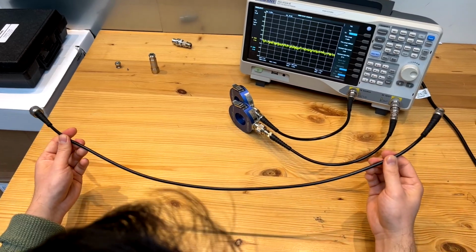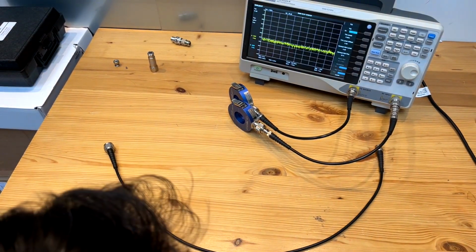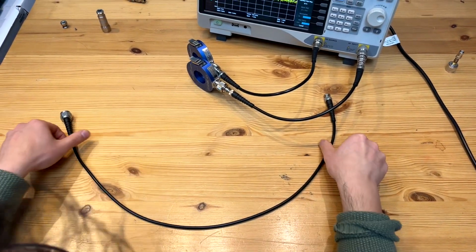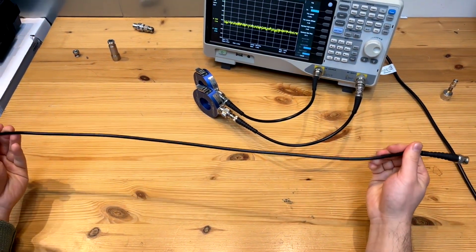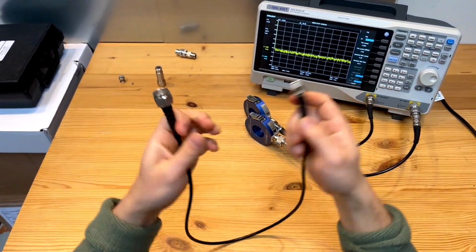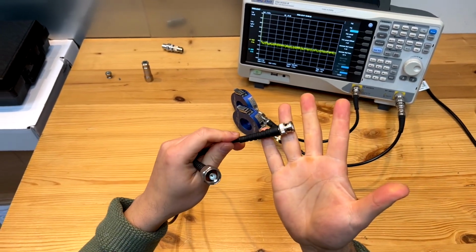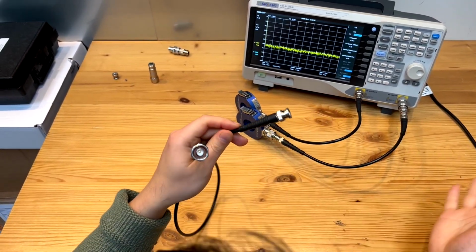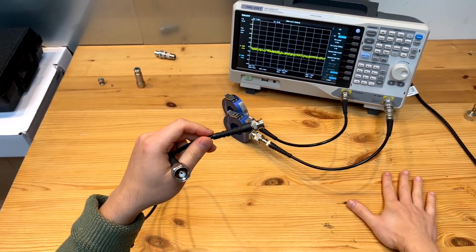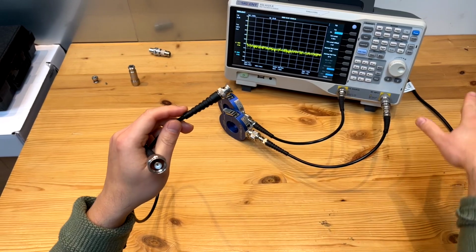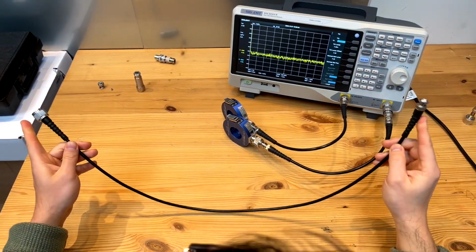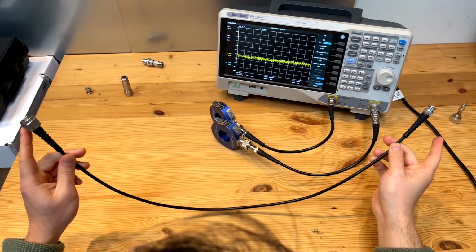An obvious way of doing it is to feed signal at the center point of this coaxial cable. Because if you look at the common mode impedance of this cable, this end and this end are open circuits. When I say open circuit, they really have a very big impedance compared to a common ground. This common ground could be the earth; in this case it's a wooden table, but actually the earth I'm standing or sitting on. So these are high impedance to earth.